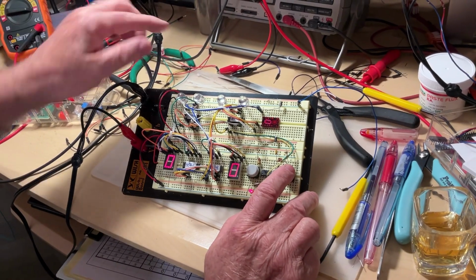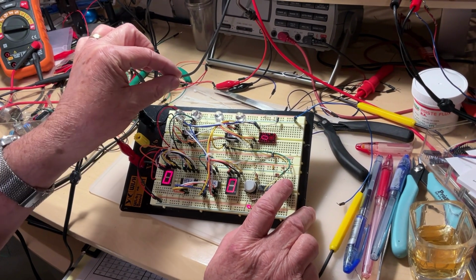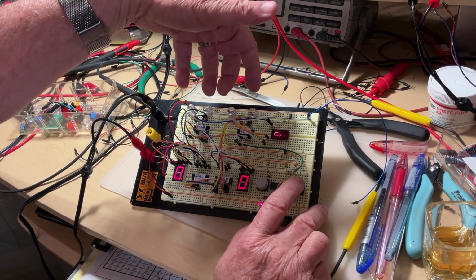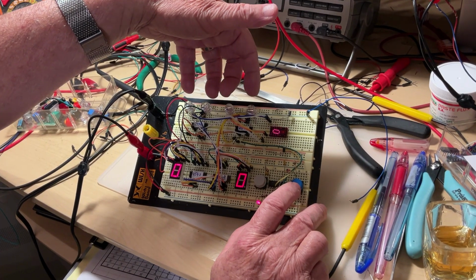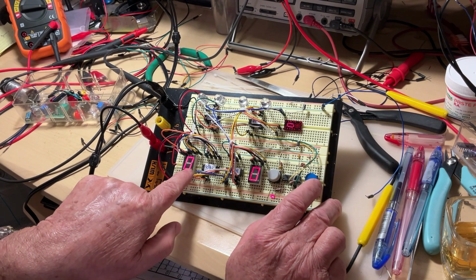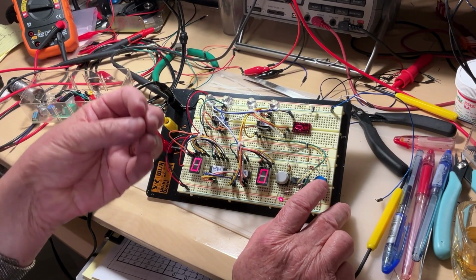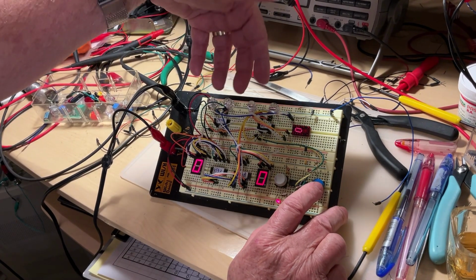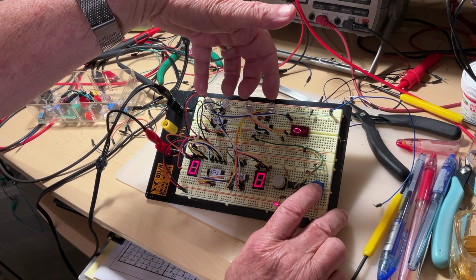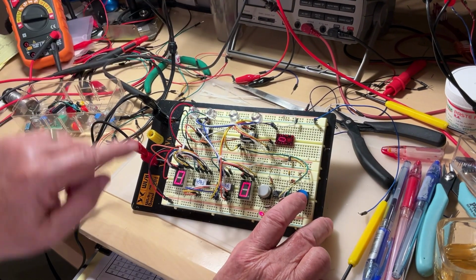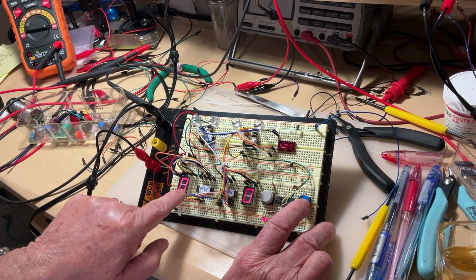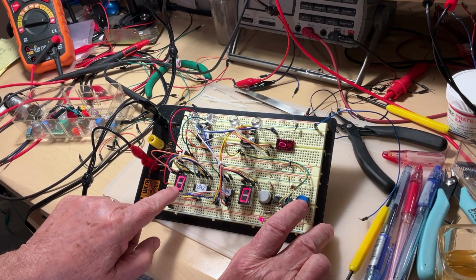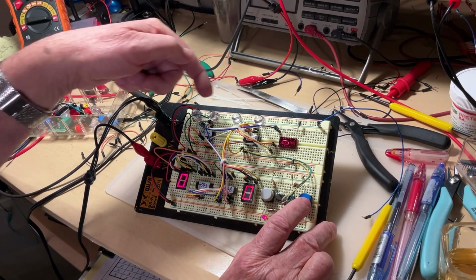Each flip-flop has connected an LED at the output. So we have 4 flip-flops, 2 in each package, so 4 LEDs. But the display has 7 segments, so we need something or somebody able to convert that information from 4 bits right here, from the 4 outputs of the JK flip-flops, onto the 7 LEDs inside the segment, and not randomly, but in such a way that it makes exactly the numbers represented by the combination in binary.